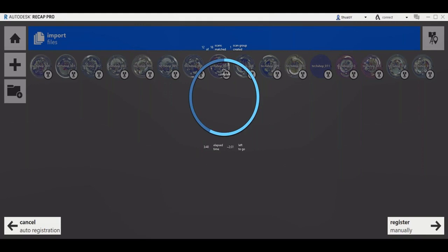So it's a good thing also for verification. Sometimes you might find that the automatic registration, if you're doing a very similar area with similar background or imagery, can very seldom connect to a very similar point that's not correct. And this is where you can manually adjust it. So you've got the best of both here, where you can use automatic registration to do the bulk of the matching for you. And if something has not been matched, then we can come into manual registration.